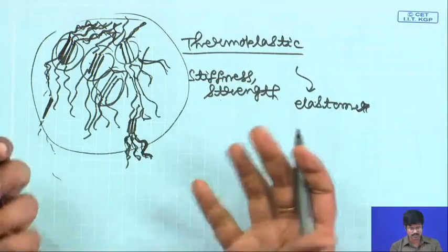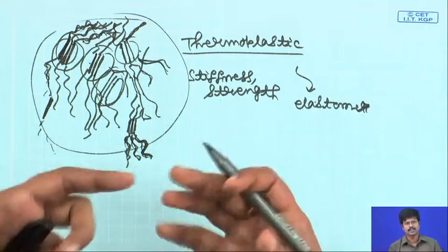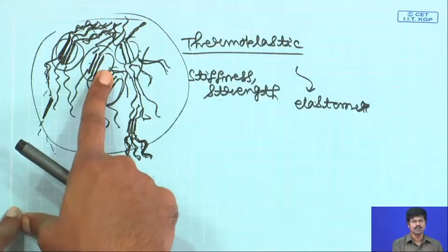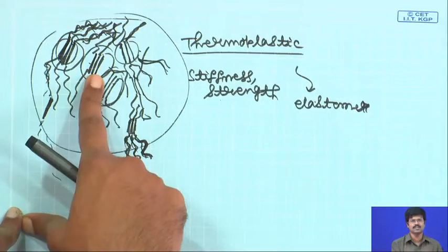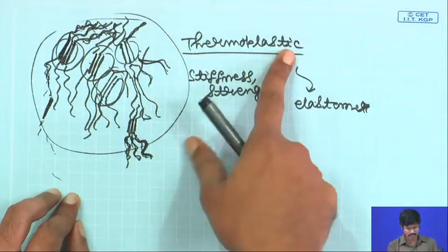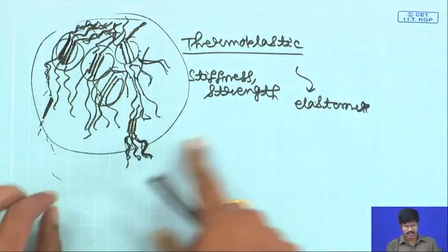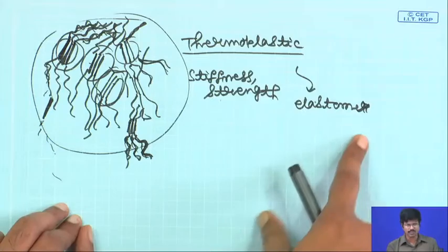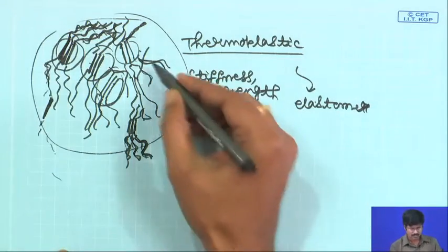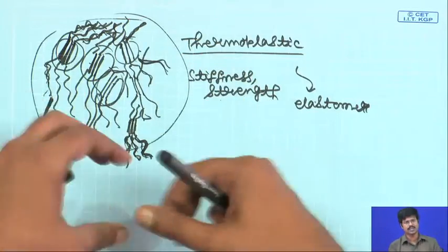Your material is not only stretchable, but also has quite high stiffness because of the appearance of these crystalline domains of hydrogen bonding interactions between the hard polyurethane segments, and the material is also thermoplastic because these interactions will disappear, these domains will disappear when you heat it, and the material is also elastomeric because you have all these soft flexible chains which can be extended to their complete length.